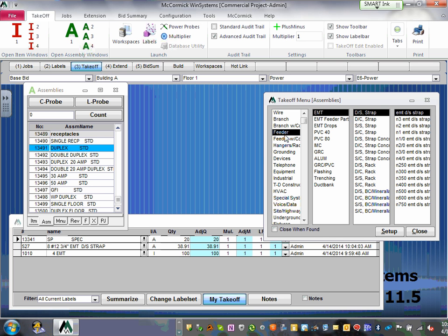I think McCormick is easier to learn than Accubid, but a lot of the industry likes Accubid. It has more detail, which becomes more cumbersome too. You can adjust a lot of stuff. For you as a beginner, I think going through Accubid is straightforward: 5 steps, and I walked you through 3 steps. Steps 4 and 5 are literally 10% of the work. You just put in the overhead, the labor, and the miscellaneous items. So really, step number 3 is 90% of your time right here. Any comments, guys? Questions? Cool.